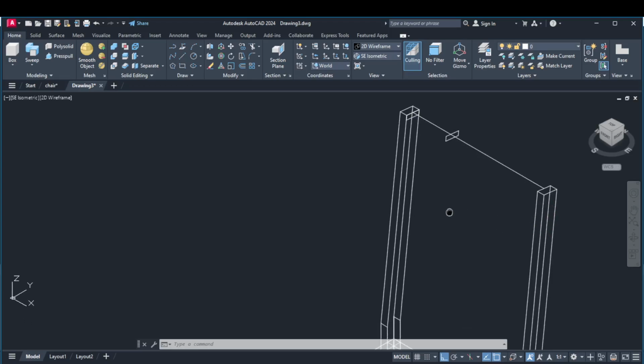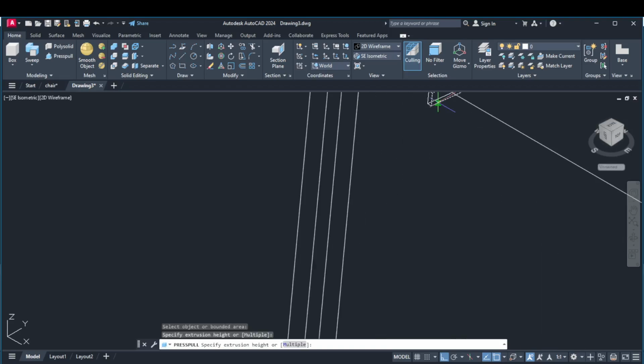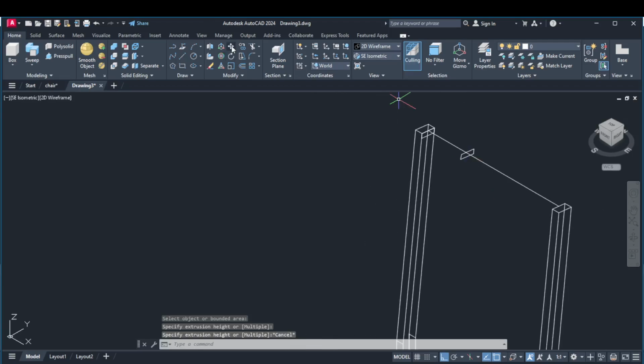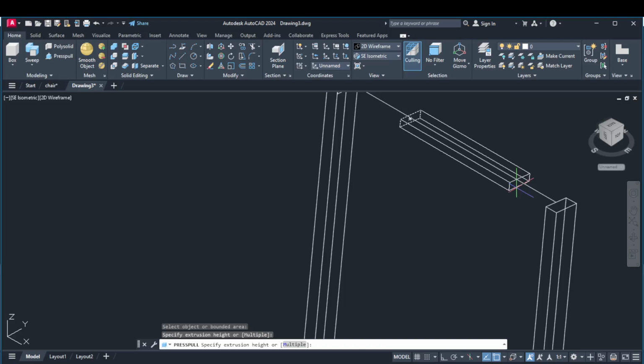Now we can press pull this one at a distance of, is it 45? 45 from end to end. Let's just press pull it by 45, then we'll see about that. Well, we can rotate it first. Let's rotate it. So pick rotate. Okay, you can just press pull it by a distance of 45. So 45, enter.